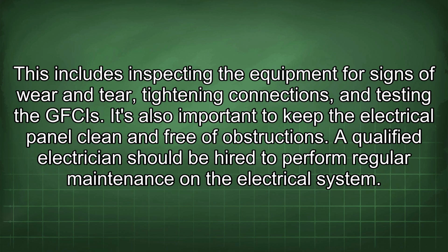Regular maintenance of the electrical system is essential to ensure its safe and reliable operation. This includes inspecting the equipment for signs of wear and tear, tightening connections, and testing the GFCIs. It's also important to keep the electrical panel clean and free of obstructions. A qualified electrician should be hired to perform regular maintenance on the electrical system.